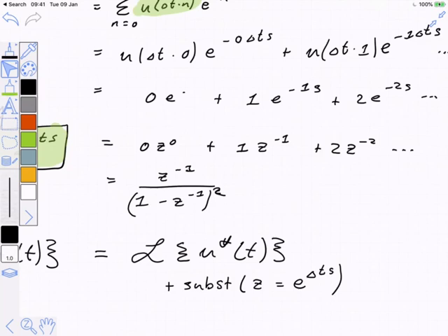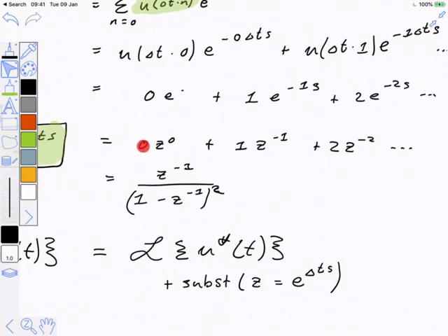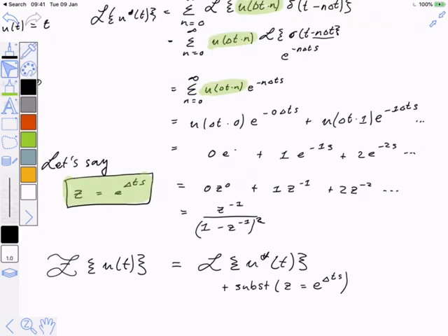That's exactly what it is. It's kind of going the wrong direction if you think about causality, but it's a one-time step time shift. That's the first thing. Z is a one-time step time shift. It's also very clear that the coefficients of the fully expanded Z transform in this form with the negative powers, each one of these coefficients is the value of the function at that time step. Right? It comes directly from this definition.